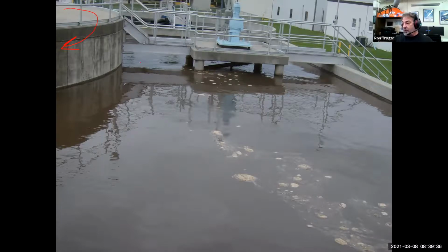But there's a mixed liquor flow of water flowing from that aeration basin into this anoxic zone, coming from the side of this basin, where we have some actual nitrate in the mixed liquor. So we start to see the denitrification take place in this first basin. If we have NO3 coming into this basin, and over here influent BOD coming in, that's the carbon coming in. So now we start to get the nitrogen gas, the N2, coming off the surface. So N2 going back to the atmosphere.